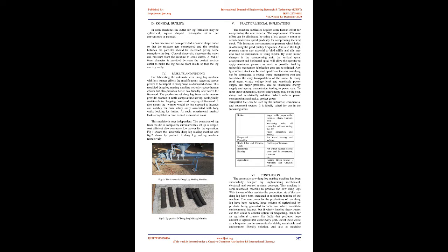To avoid the problem of ramming, mixing blades are provided inside the hopper, which rotate as the machine is started. The blade angle depends upon the diameter of the cone and may vary according to the shape and diameter taken in various machine designs. The blade is taken such that it should not touch the surface of the hopper. The blade rotates with the help of the sprocket arrangement. A chain is provided on the sprocket to transmit the power to the mixing blade.